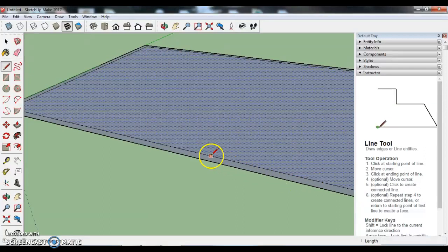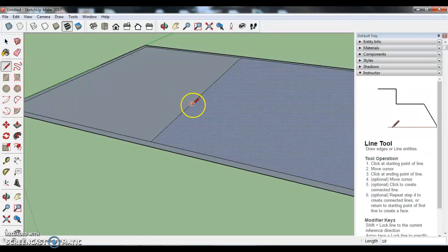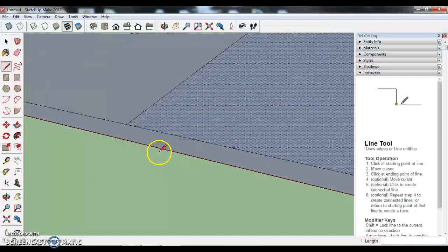If I wanted to divide this room exactly in half, I could go right there, but I'm not going to. I'm just going to start here. I'm going to click once, and it'll snap parallel to that other edge, and there it snaps to that, and that looks pretty good. So this wall needs to have some thickness as well. Specifically, I want it to be 4.5 inches thick.